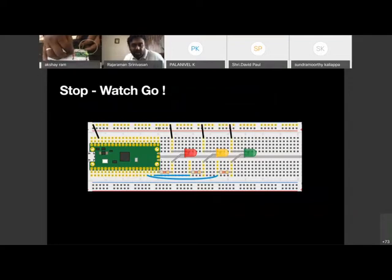Because this entire line is connected, you are actually connecting a resistor from here. The other end of the resistor is connected here. On the same row, you need to have the LED. Basically, instead of connecting this LED's anode directly to this output, you are connecting it using a resistor.